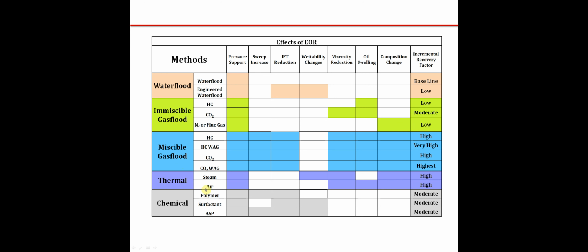Thermal, yes, for viscous oil so far, so long in the world, thermal has been the mainstay, whether it is shallow or deep, steam and air. Air injection has now moved from heavy oil to light oil, and many operators are testing it in medium gravity too, where polymers are not effective because the temperatures are either very high, or it is too deep, or reservoir pressure has declined.